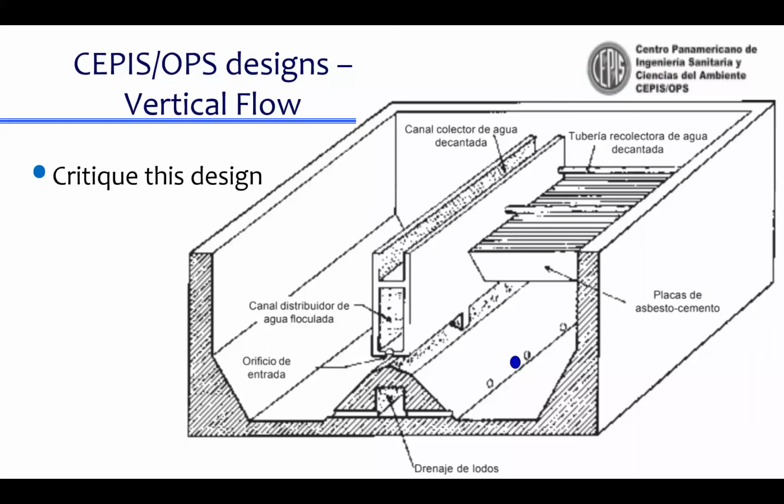Would it cause a lot of those particles to build up at the bottom, and they have to go inside there and wash it out? But the sedimentation plates would also make it hard to get in there and clean all that stuff out. Yeah, lots of good comments there. Sorry, I missed your comment, Eric, earlier. Yeah, so there would be sludge accumulating on that flat bottom. You now know that if there's a flat surface, sludge is going to accumulate on it.